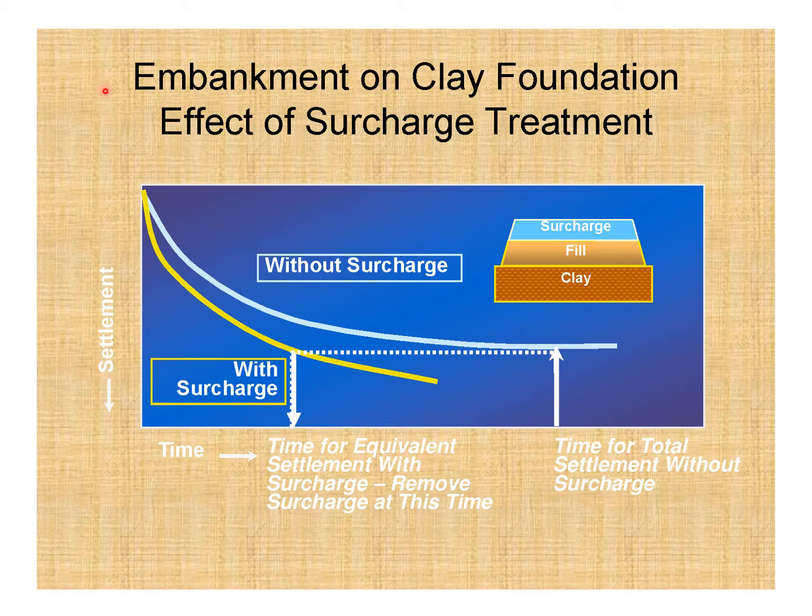Embankment on clay foundation, and if you just look at the effect of surcharge treatment, when there is no surcharge, you can see with the passage of time the settlement is like this, and at this particular time you have got this much settlement. But if we place surcharge, you could get that much settlement in a shorter period of time. So that is the basic theme of preloading.